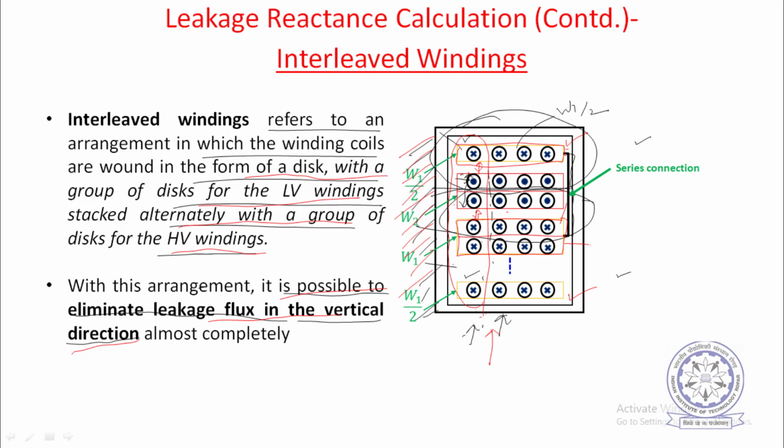Now horizontally, if you can see, this is the winding here. So here all conductors of one polarity are there. So the MMF must be increasing along this, and then across the air gap it should remain constant, and then again here opposite current, so it must be decreasing and then going in the opposite direction like this. So here the MMF in the horizontal direction will not be 0.